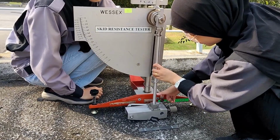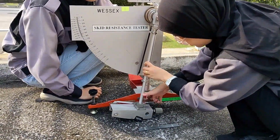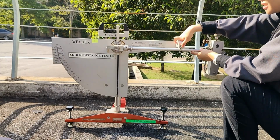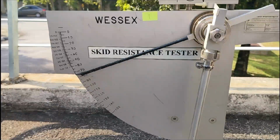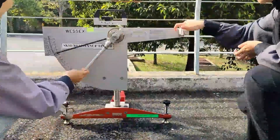Step 3. Make sure the friction foot is in contact with the road surface over the precise distance, as shown in scale rule, which is placed alongside. First, start at a smooth surface. The pendulum arm was released. After it has swung through, the arm was caught in order to prevent a back swing. The reading was taken and recorded. The test was repeated until 3 readings were obtained. The same step is repeated at the same place for the wet condition.